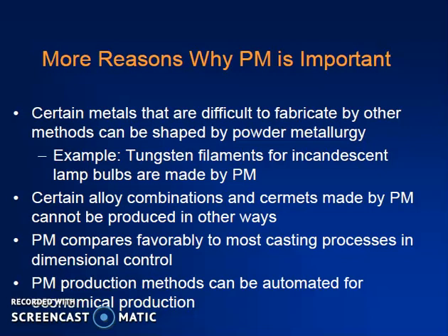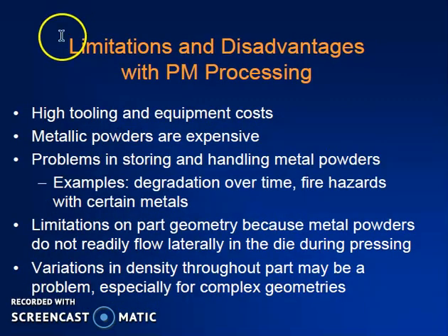Powder metallurgy compares favorably with most casting processes in dimensional control, and powder metallurgy methods can be automated for economical production. So, these are the reasons why powder metallurgy is highly appreciated by any engineer. But there are some limitations as well as disadvantages with this technique. These limitations include high tooling and equipment cost. When we prefer this technique, the tooling cost as well as the equipment cost is very high.